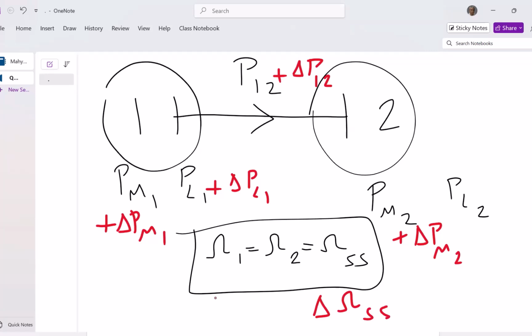So we have one change in one area that causes all of the areas in the system to respond to that, okay? Now, let's compare this with the conditions that we expect in our system based on the contracts that generally exist between different areas of the system. Based on the market, we know that the power system is working based on a market. So there is a power market. Based on that market, area 1 and area 2 are going to have some transaction of power between each other. So for example, P12 is supposed to be 100 megawatts going from area 1 to area 2.